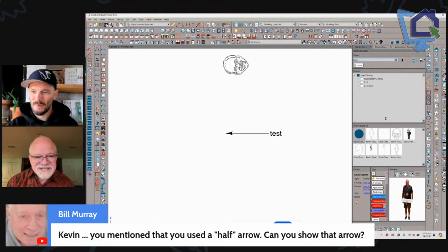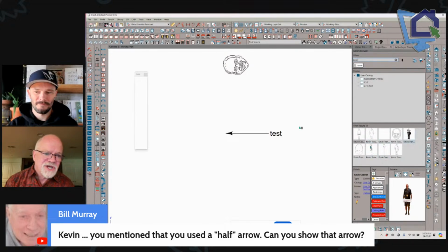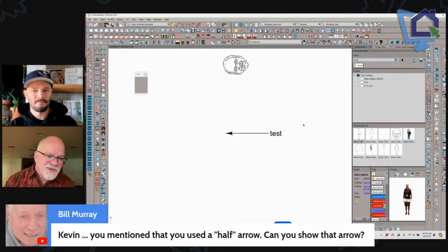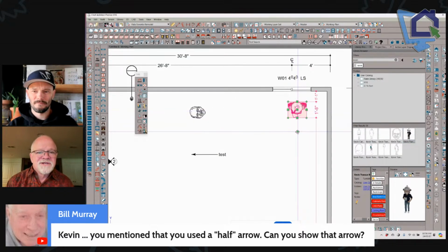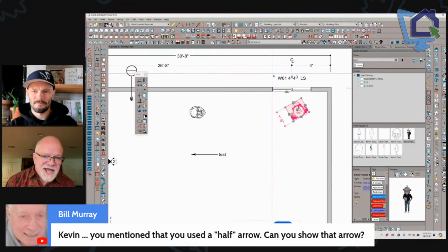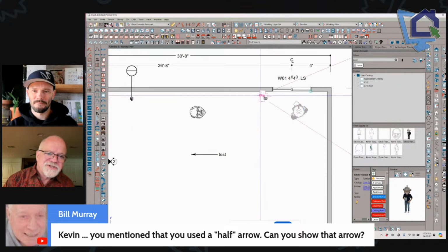Anyway, those arrowhead types are relevant to the type of document or the type of measurement that you're showing. A tick mark is very easy to see and use, especially in a drawing where the angles are all perpendicular to each other, like rectangular rooms and lines pulled off of them. There's no confusion in seeing an angled arrow in the form of a tick mark.